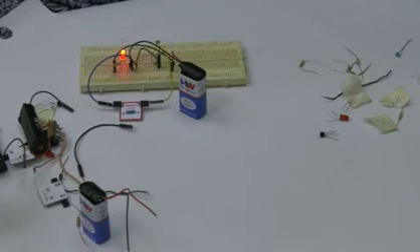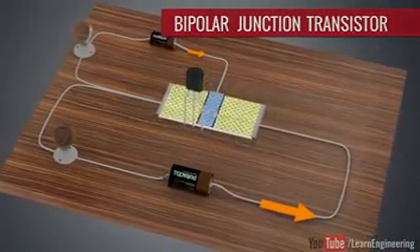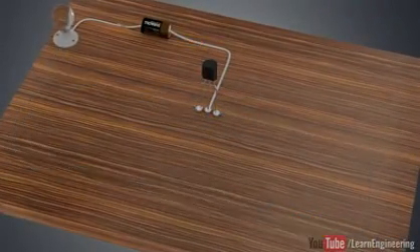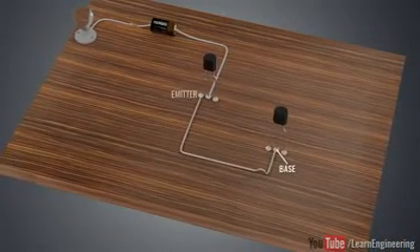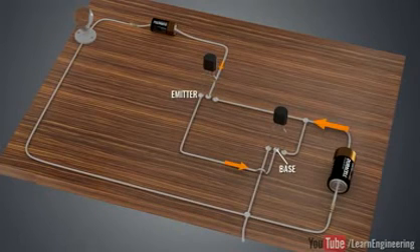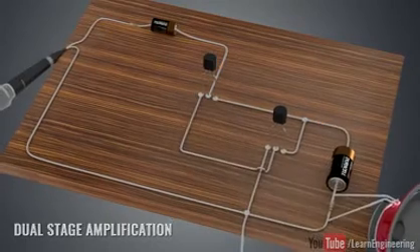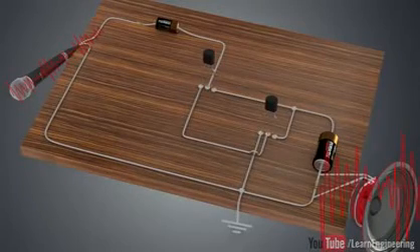We would summarize the transistor application as an amplifier in the video that follows. Replace this representative transistor with a realistic one. You can further improve the amplification by introducing one more transistor. The base of this transistor is connected with the emitter of the first transistor. If you introduce a weak fluctuating signal at the input, like what you would find in a microphone, you will get an amplified signal at the loudspeaker.